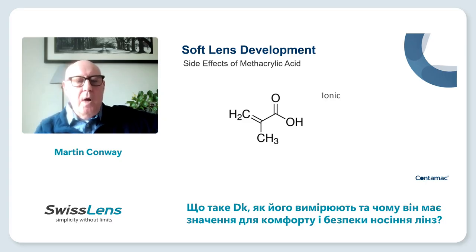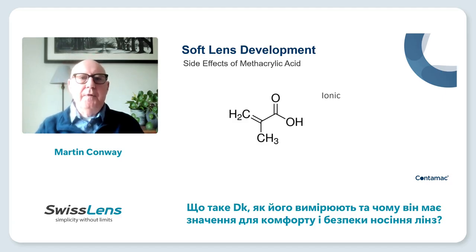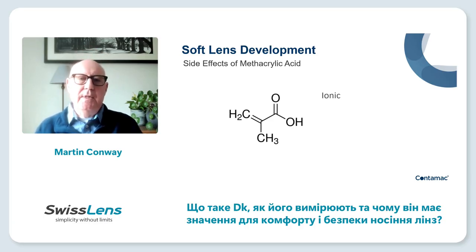The problem was, whilst this was a benefit within the matrix of the lens, on the surface, it meant that the surface of the lens carried an ionic charge, a negative charge. And this attracted positively charged molecules from the tear chemistry, namely protein. So these early methacrylic acid-based materials were prone to protein deposition.